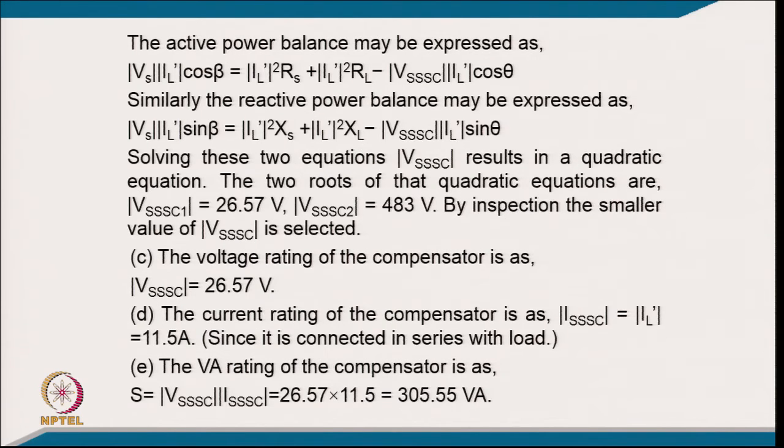So, the active power balance may be expressed as: the active power on the supply side is equal to the loss in source impedance, the loss in the load, and the active power injected by the series compensator. Similarly, for reactive power, it is the reactive power consumed by the source impedance, the reactive power consumed by the load, and the reactive power injected by the compensator.